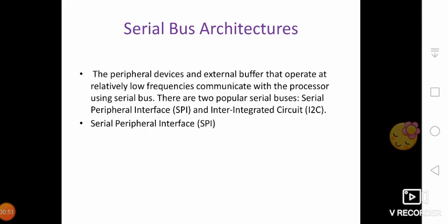So Serial Peripheral Interface SPI is an interface bus designed by Motorola to send data between microcontrollers and small peripherals such as shift registers, sensors, and SD cards. It uses separate clock and data lines along with a select line to choose a device.